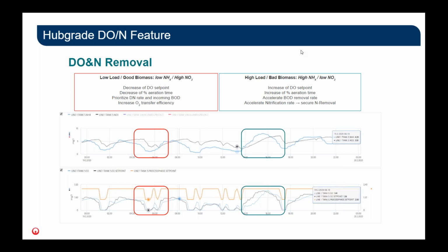So if you have an effluent total nitrogen permit value and an effluent ammonia value that you have to meet in your permit, the system will ensure that you're staying underneath those values. And then it's always working to keep things optimized and balanced to as great a degree as possible, given your current actual conditions, and stay in between those extremes.